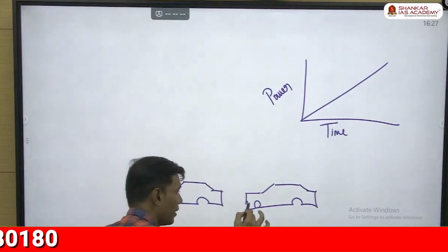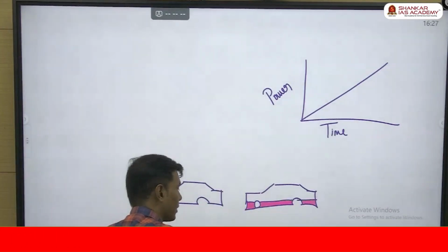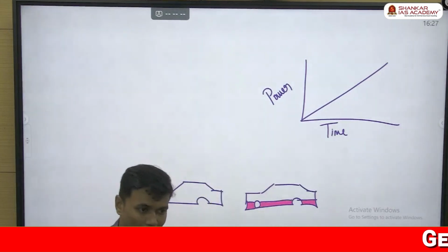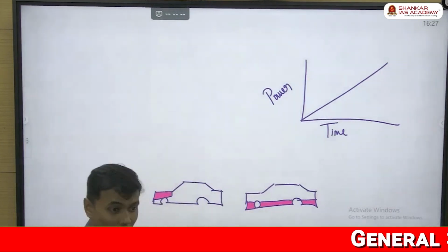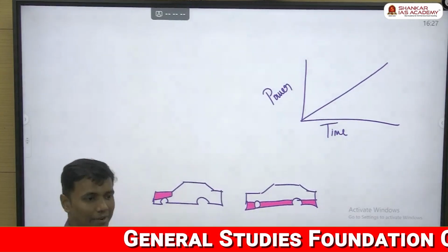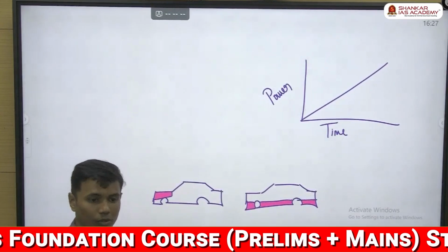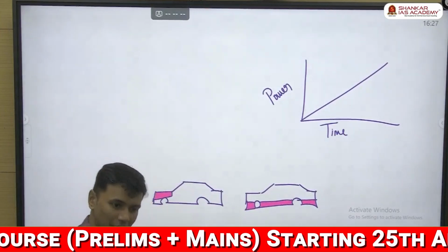But if you take an electric vehicle, you are sitting on battery packs. So battery packs are lying low and the entire weight of the car is very low. Even when you go at 70, 80 kilometers per hour, if you're going to cut through the barricade, you won't have the body roll. And most of the time the car will not roll over. That's because most of the weight is lying at the bottom.